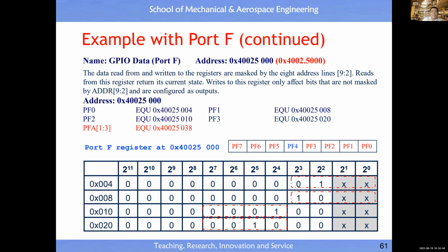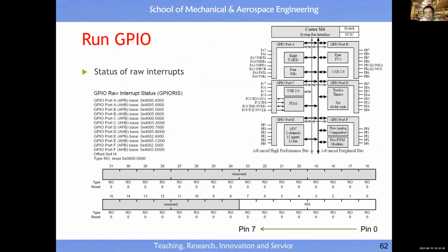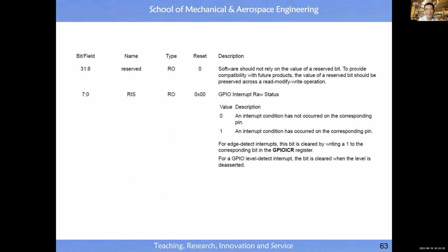Okay, this just gives you a more detailed explanation, all right, of the previous slide. Okay, in case let's say 3A corresponds to what? 3A corresponds to the selection of pin data bits connected to pin 1, pin 2, pin 3 of port F, right? That's it. Okay. And after that, then just run. Once you run, actually you can monitor internally generated signal, right? And for example, whether the input has data appear or not, because once you press the button or not. So here basically showing you the internally generated signal by the input device, etc., right?